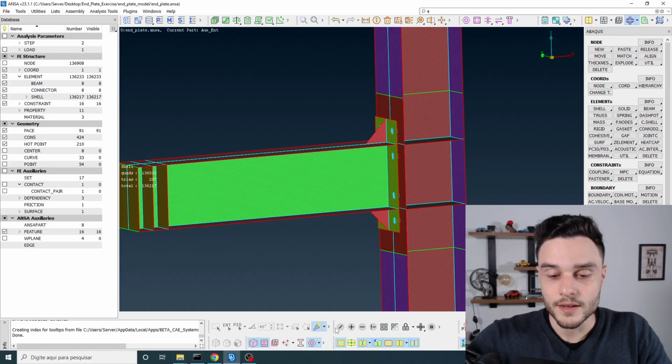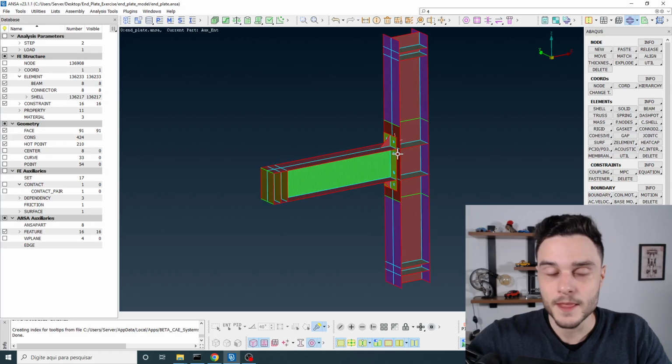And in the yellow buttons, where we control the visibility of cones and points, be sure that you have everything that I have activated here. And in this drop-down list, deactivate spots. I don't want to see spots, so that this model looks cleaner.